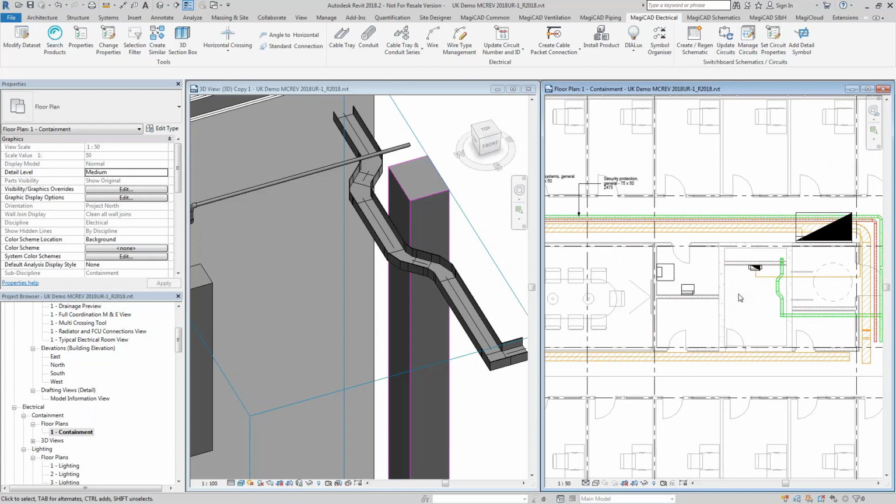With the electrical module, there is only one type of product that this will work for, which is conduit. That's because the standard connection tool will find the best method to connect two circular objects together. So if it was circular ductwork or conduit, it can rotate fittings, use the least amount of fittings, and connect things together.